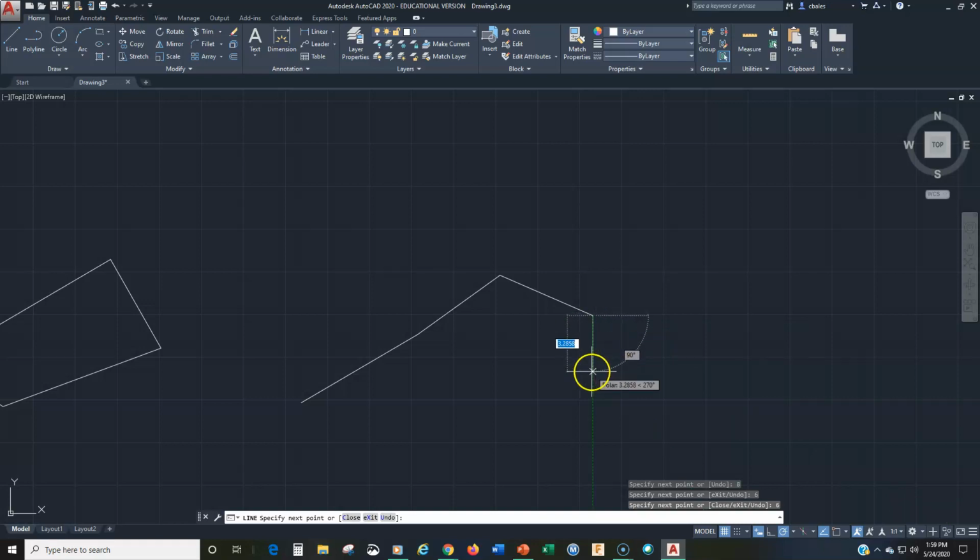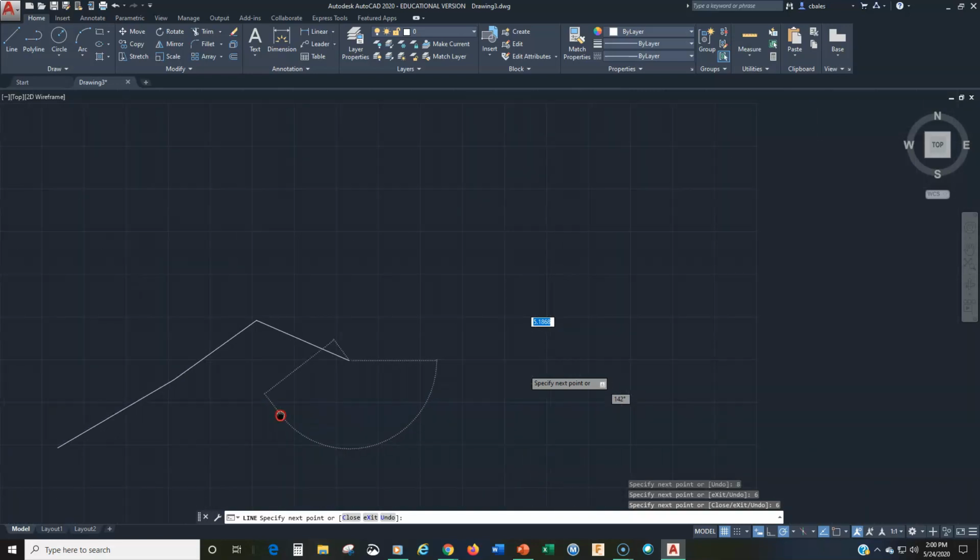But it's also very inaccurate because I don't know what angle I was just drawing at. And when it says that it's drawing at 15 degrees, it's not really 15 degrees or 20 degrees because I'm freehanding it there. AutoCAD only shows you a certain number of decimal places. That doesn't mean that the other decimal places are all 0. Okay, so I can never really be sure of my accuracy doing that method until and if I use my polar tracking.